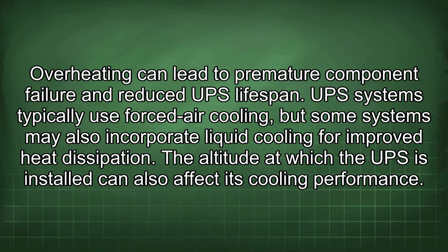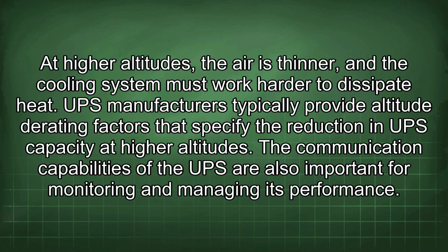The altitude at which the UPS is installed can also affect its cooling performance. At higher altitudes, the air is thinner, and the cooling system must work harder to dissipate heat. UPS manufacturers typically provide altitude derating factors that specify the reduction in UPS capacity at higher altitudes.